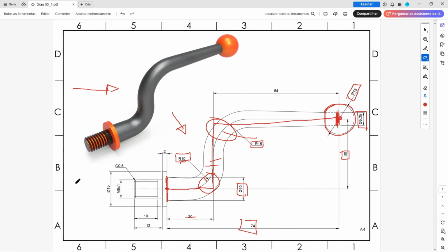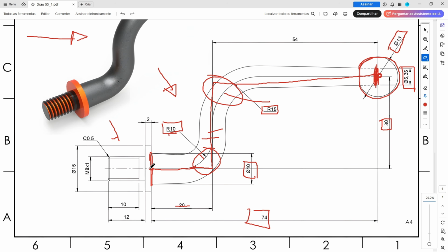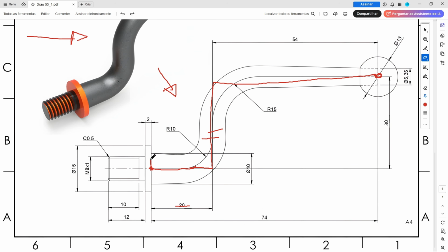And now we will select the right plane and create this part here. So in this sketch, we will create a line here and a line here. This line has 2 millimeters and this one has 15/2 because we use the revolve to make this profile, this part, okay?